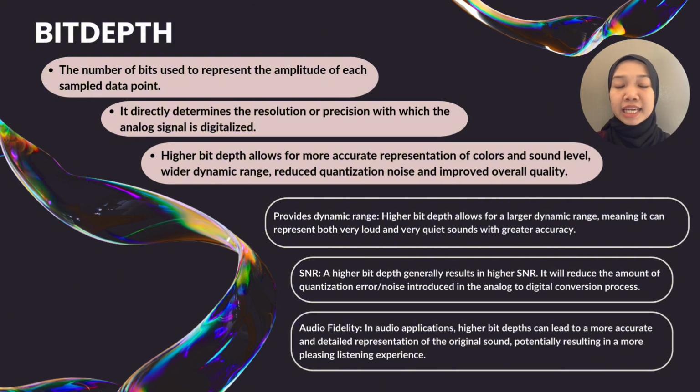Assalamualaikum and hi, I am Aina and I will continue the presentation with bit depth. Bit depth is the number of bits used to represent the amplitude of each sample data point. It directly determines the resolution or precision with which the analog signal is digitized. Higher bit depth allows for more accurate representations of colors and sound levels, wider dynamic range, reduced quantization noise, and improved overall quality. Why is bit depth important?